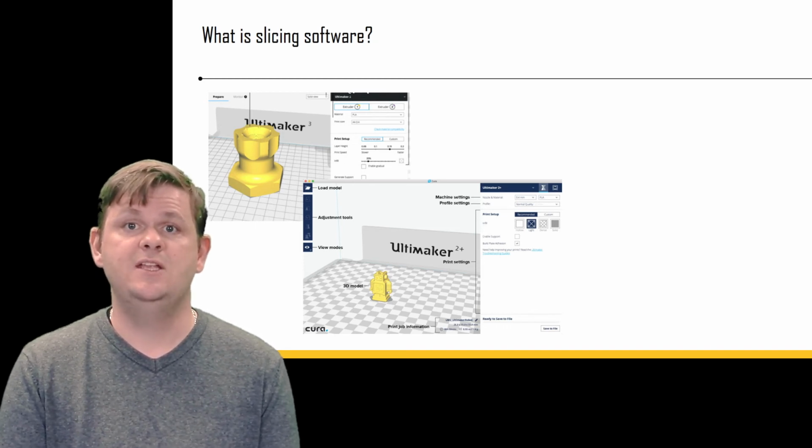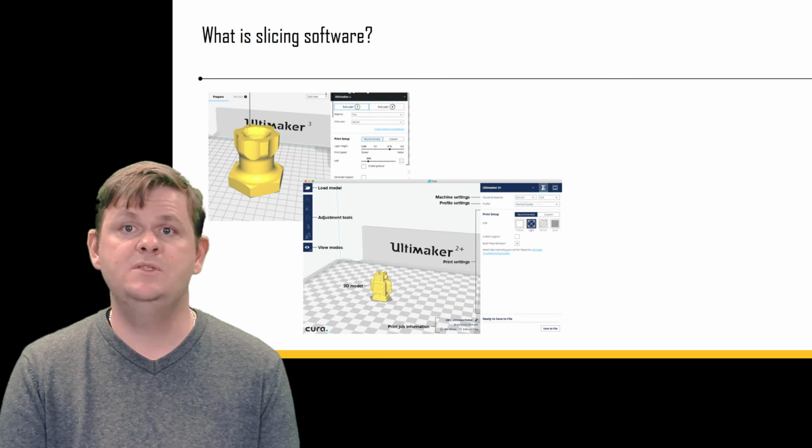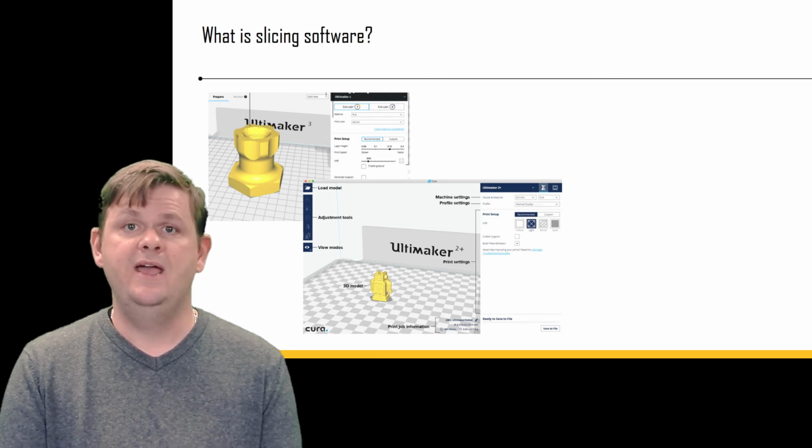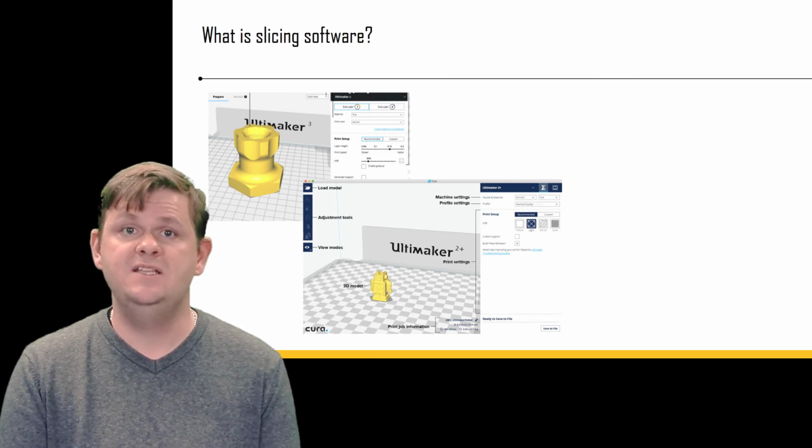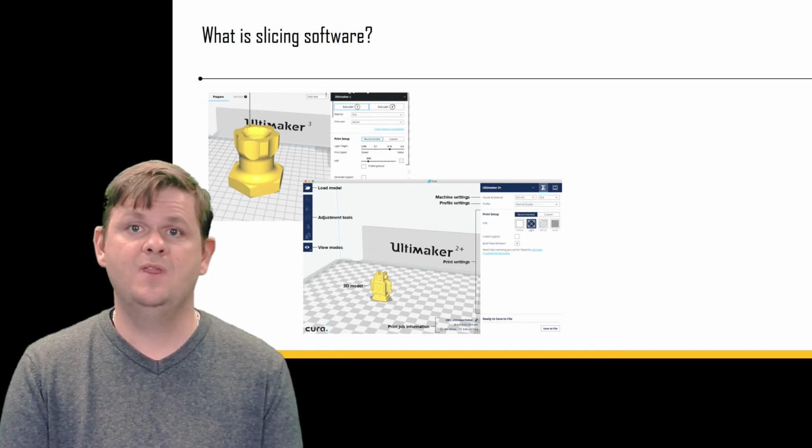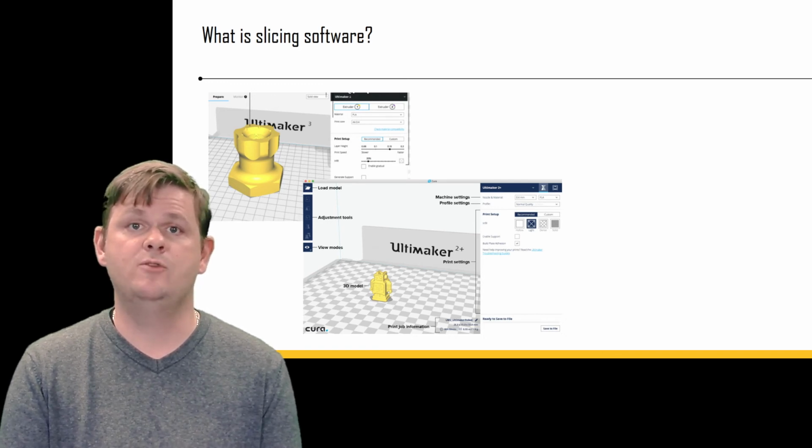Each setting change informs the end result and impacts the finished print. As a minimum, slicing software enables us to rescale, position and orientate a part. It also enables us to select and increase the density of infill and support and alter printer material settings. Slicing software may also encourage variety and experimentation with additional features which enrich, optimize or improve your part.